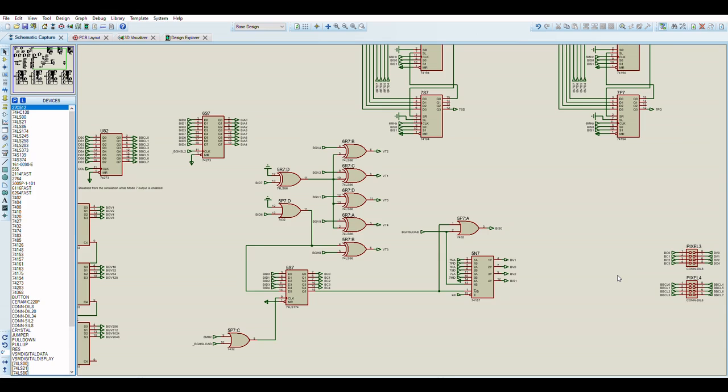The character and the tile layers do not do this test. All they do is output the lower 3 bits from the 3-bit planes for the character or tile data, and they output the red palette index.